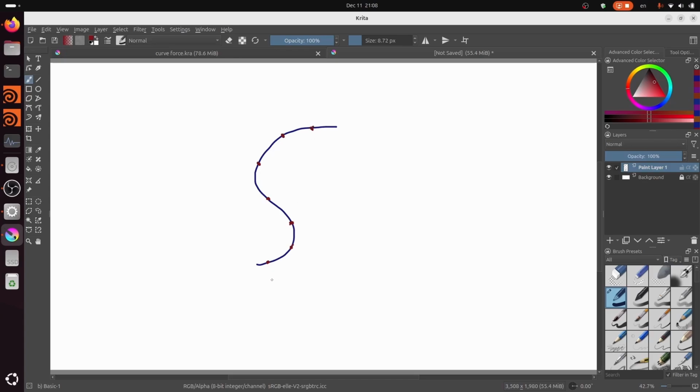By default, the points are ordered along the curve. So this is 0.1, this is 0.2, 3, 4, 5, 6, 7. So now we have 7 points, but actually the numbering starts in Houdini from 0. So the first point will have the number 0, because this is going to have significance.